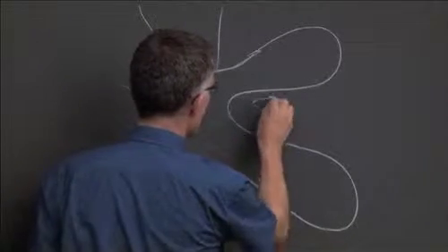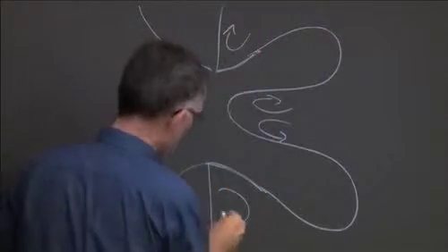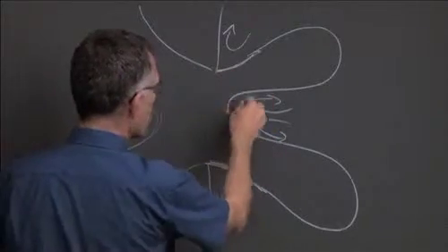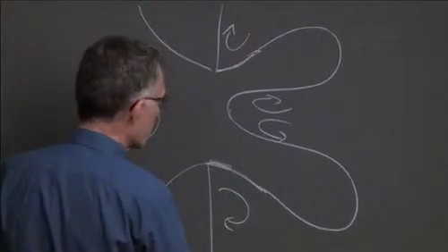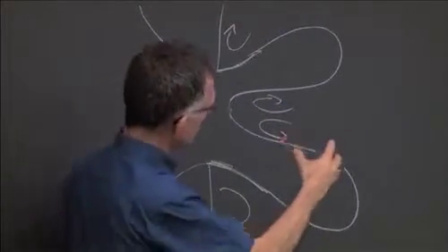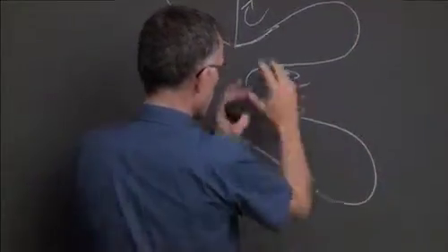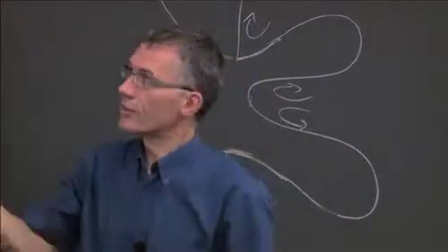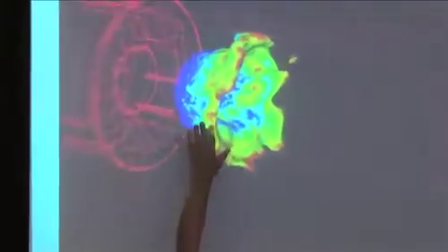And it's due to the fact that you are recirculating here and recirculating there. Depending on the case, you will see flames stabilized here and here or not, but you will always have this zone here. Actually, the flame has to stay there. Remember, we use recirculation to keep the flame anchored here. So now you look at that with an iso-surface of temperature, you're looking at an animal which has this shape in 3D. It's like a donut without a hole in the middle. I don't know. It's this guy, okay? You see there's a hole in the middle, and that's a flame surface colored by the velocity.